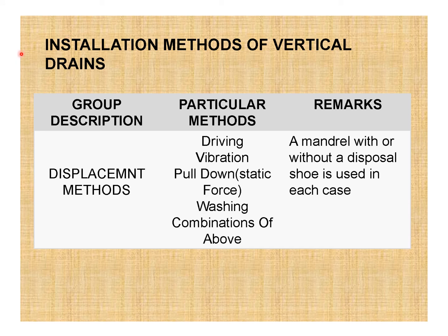Now, the installation method of vertical drains. So we have different groups like the displacement method, where we have driving, vibration, pull down, static force, washing, and a combination of the above.